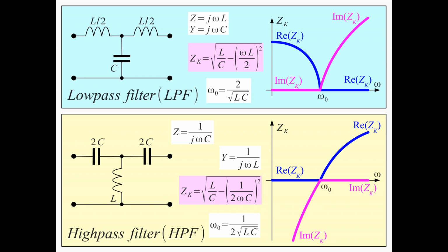Making a bandpass filter now, it does not make sense to concatenate a low-pass filter and a high-pass filter. That does not make sense. Rather, we build a high-pass filter with its proper components.